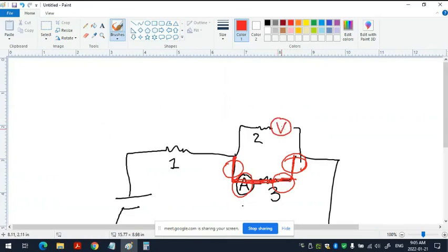Is this correct? No, because that's how you place an ammeter. How do you place a voltmeter? Remember yesterday when Tariq and Nadim held them and I used my fingers as hooks. Where did I place them? Two touching points. Exactly. So that means what? Undo, undo.